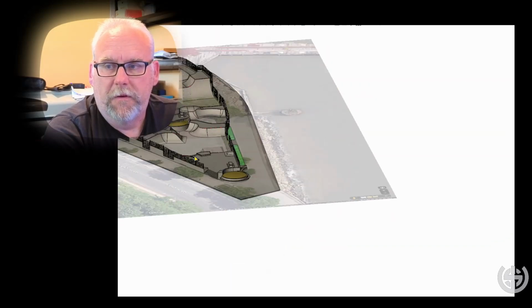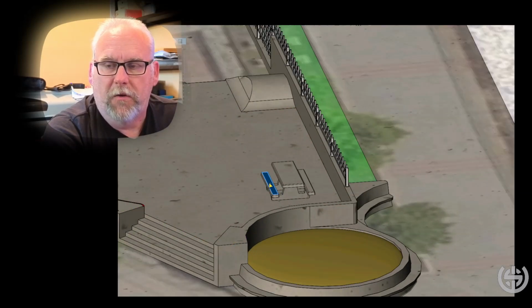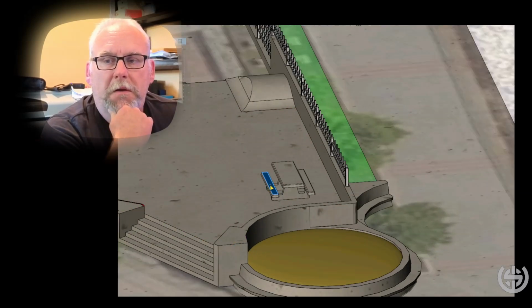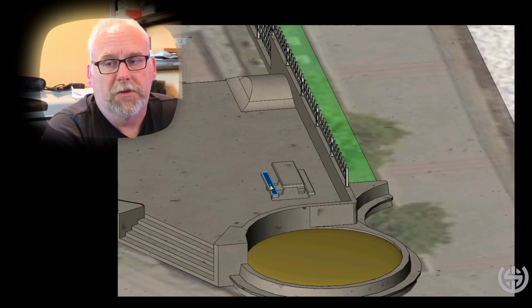Part of the design here is these concrete picnic benches. So these are purposely selected. Concrete picnic benches are durable. If I were the city, I would get all concrete benches, meaning that their entire structure is made out of concrete. They wear well. They can't be moved, so kids aren't going to pick them up and move them around the park. If they grind them, they're not going to snap, chip, or dent or get paint off of them.